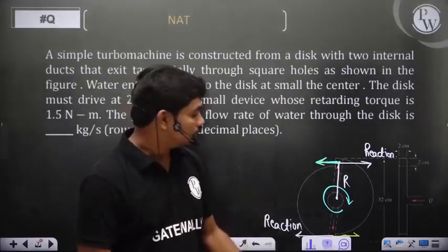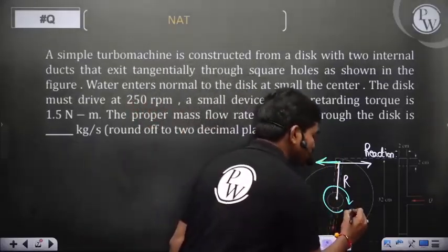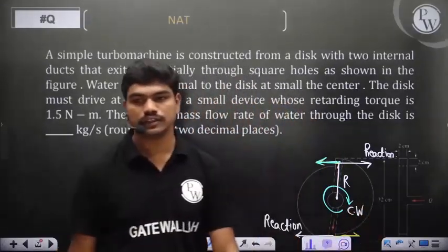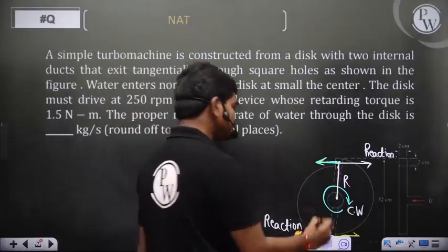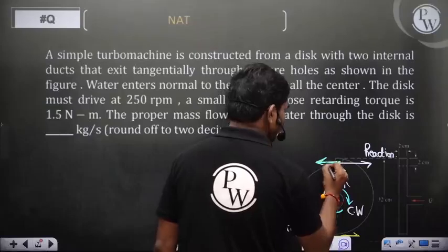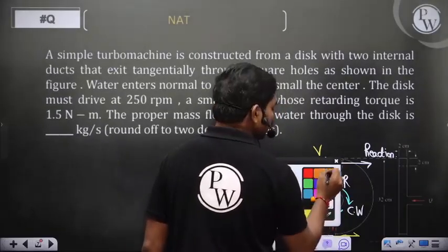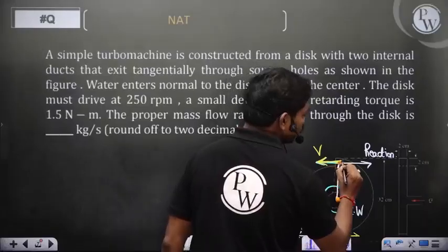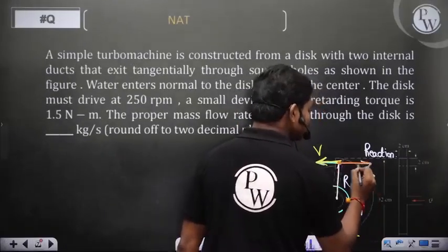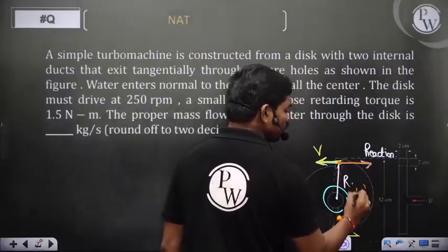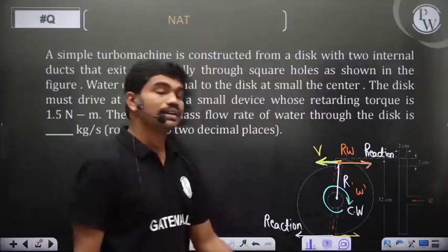So that's what you have. So basically the reaction forces will rotate this disk in the clockwise direction actually here, like this. So this is clockwise. So yahan tak sabko clear hai ya nahi? So when fluid is trying to come out with a velocity v, this point or this disk will actually try to move in this direction tangentially, because at every point it has the velocity. So let's say if this disk is rotating at an angular velocity omega, and if this radius is r, capital R, so capital R omega would be the velocity of this point.